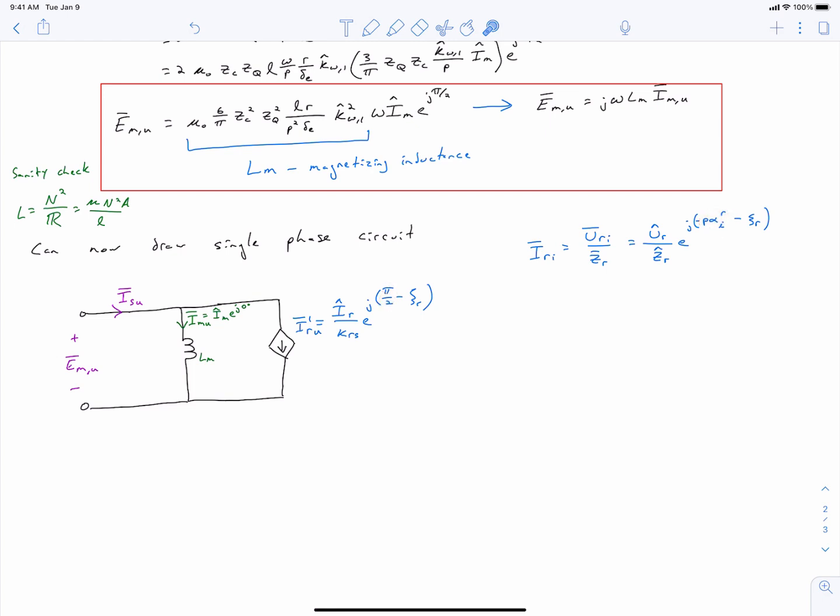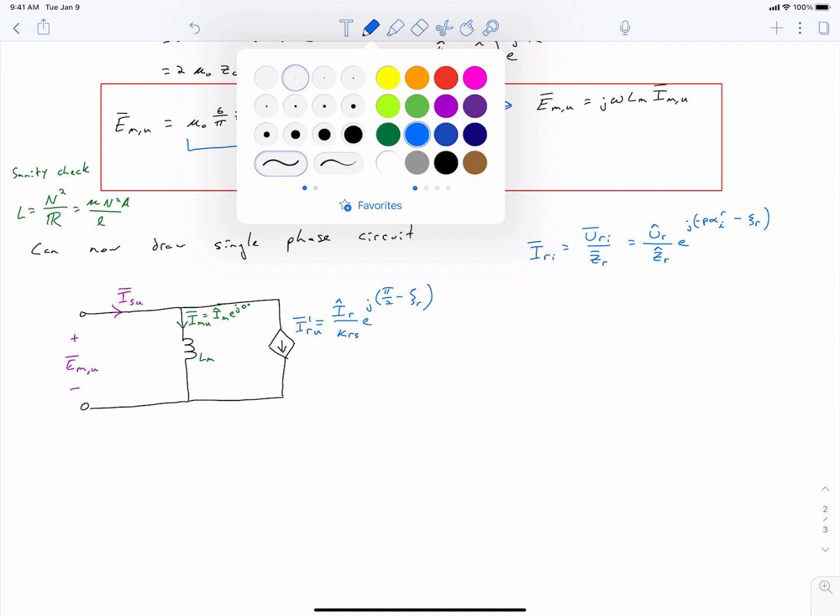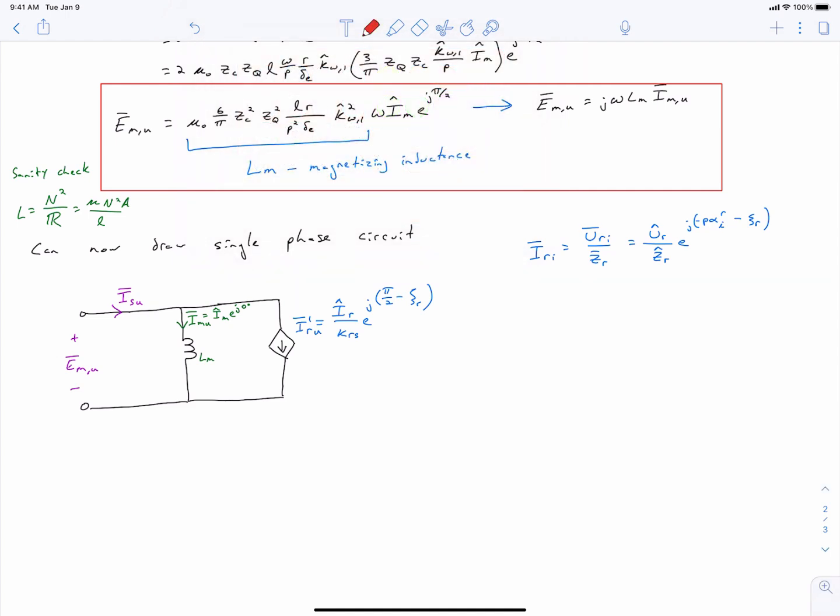And so what we can do is arbitrarily choose to think about a rotor phase or a rotor bar that is at angle P alpha I equals negative pi by 2. And if this bothers you, you could imagine that you've got your rotor already rotated to some arbitrary angle to get you this phase offset. But at any rate, it's general and proper to say that you can make this expression right here be pi by 2, so that you're studying a phase that has this characteristic.